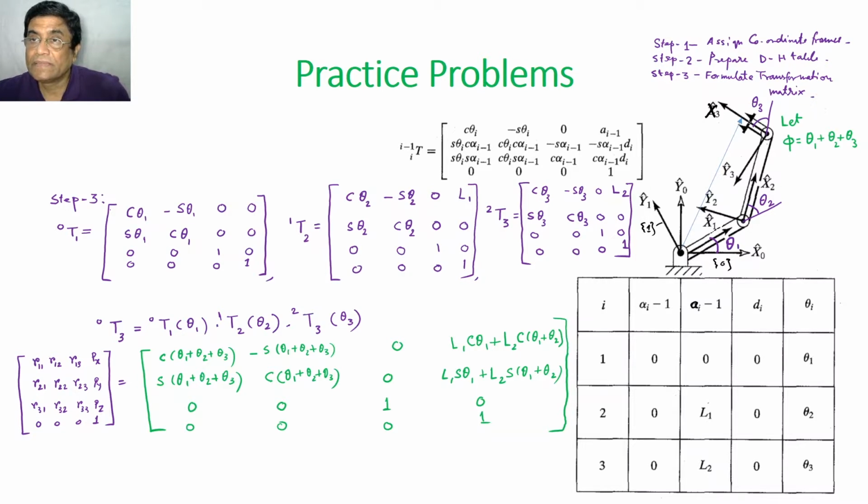Now you see, this structure can have a pose. Pose means position and orientation. And what is the pose orientation phi? Theta1 plus theta2 plus theta3. This is the pose. So any point here I can put x, y, and phi. So this will be my input.